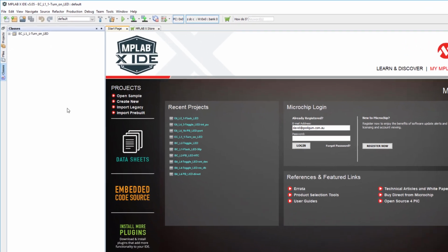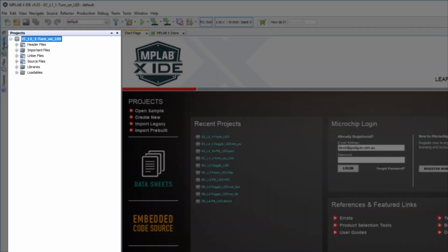your project will appear in the Projects tab. It's where you can access all the files, such as source code, that belong to your project. Source files contain the code that's compiled by the compiler. So we need to create at least one source file for each C program. You could just type them in from scratch. Luckily Microchip provides templates that you can use as a starting point.